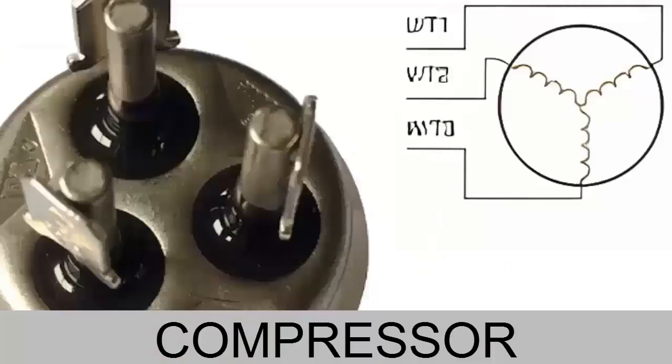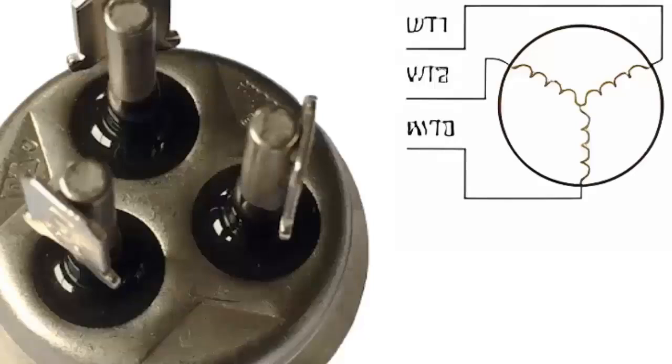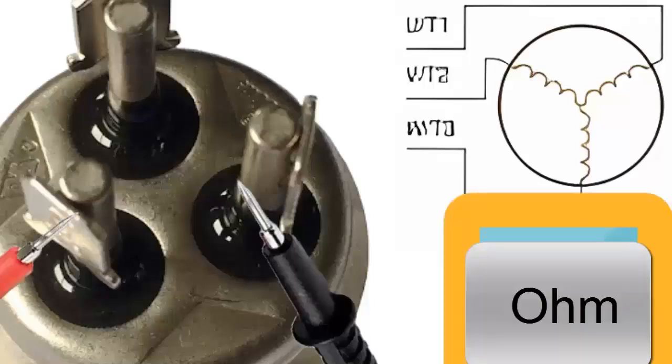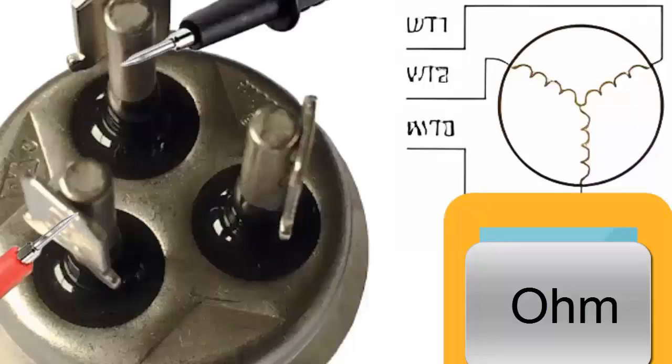Diagnosing compressor inverter coils. 1. Identify potential coil faults. If the compressor coils are open, shorted, or grounded, the compressor is damaged. 2. Perform resistance measurements on the coils. 3. Even if no obvious issues are detected, internal coil faults may still exist. 4. In an inverter compressor, resistance measurements should be very close or nearly identical across all tests.